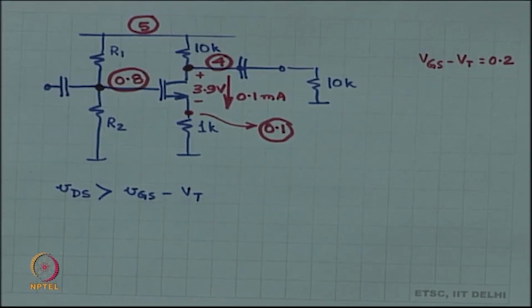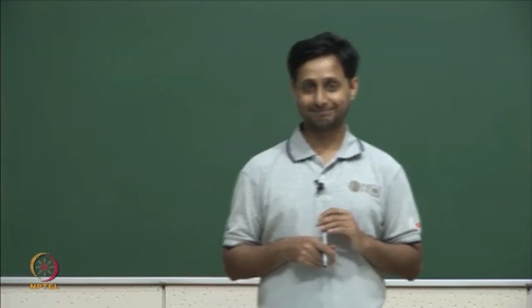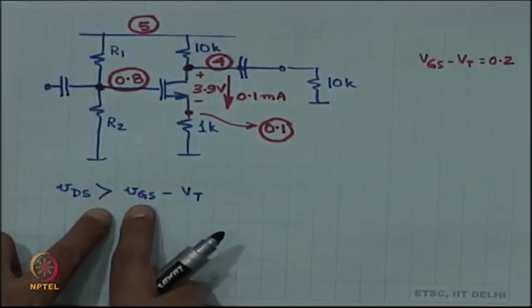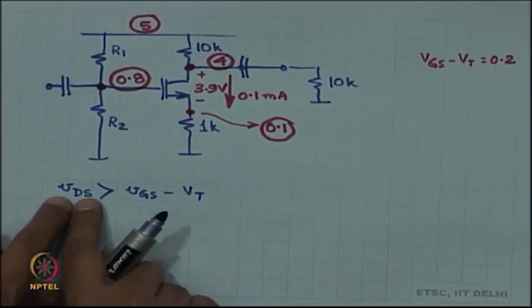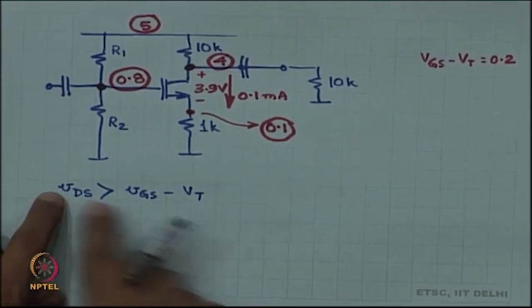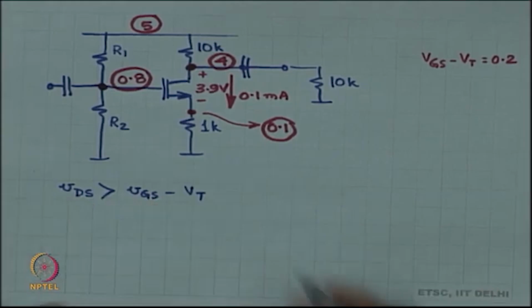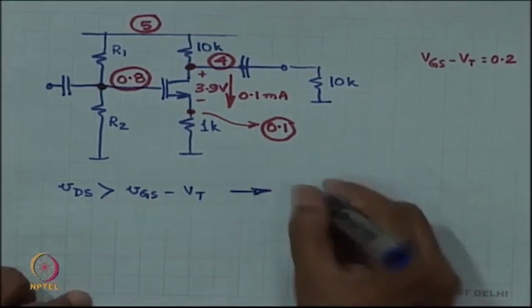Okay. So earlier we had the source as a static voltage, now the source is no longer static. But the cool thing over here is that the source voltage is going to cancel out. VDS is equal to VD minus VS, VGS is VG minus VS. So the source voltage really does not matter, it cancels out.